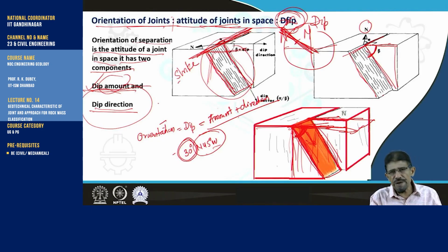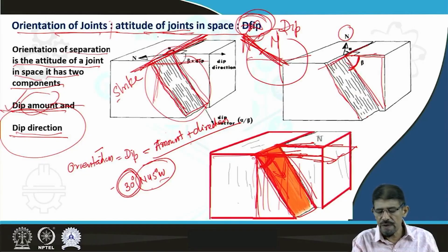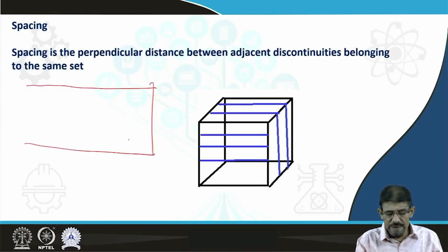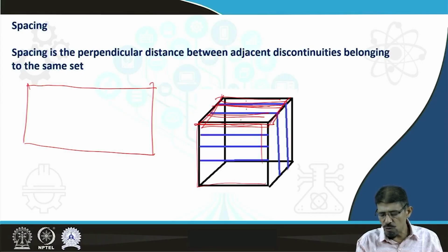Dip is very important from our geological point of view to measure the attitude of joints, or the attitude of any features present in rock strata, either bedding, lineation, foliation, etc. Suppose any strata is traversed by joints, in a vertical section we take this zone, any plane, then we can see two joints dividing this surface into 1, 2, 3.